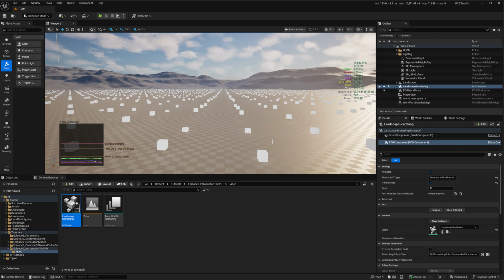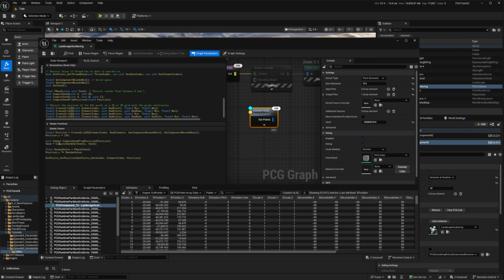We want to do the same, but on x and y. For that, we need to define, like in Transform Points, what are the min and max displacement values. I'll choose 500, meaning that my points can be randomly displaced by up to 5 meters on x and y. You have access to the lerp function in HLSL that does a linear interpolation.